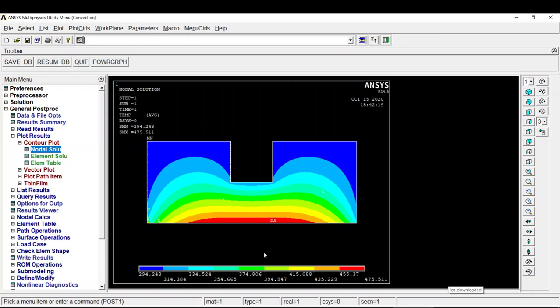So we applied 1000 watts per meter as a heat flux, and applied the surrounding temperature as 293 Kelvin by means of air, and the heat transfer coefficient between the fin and the atmosphere is 40 watts. So we will get the output like this. Thank you.